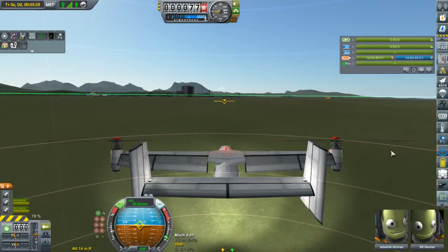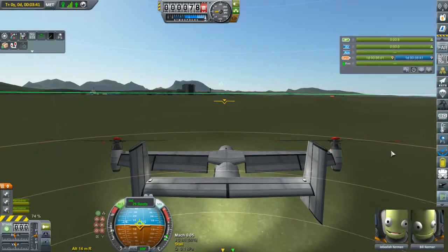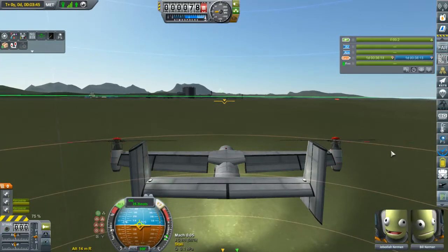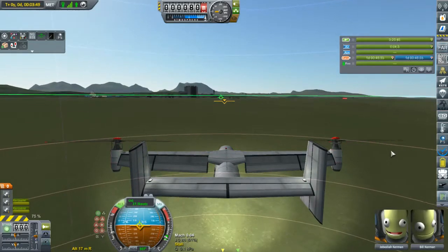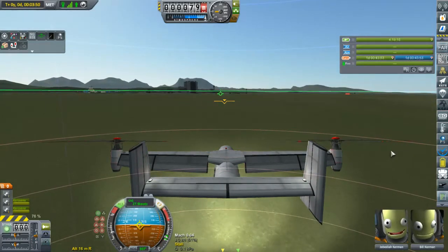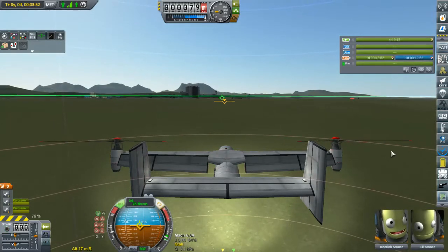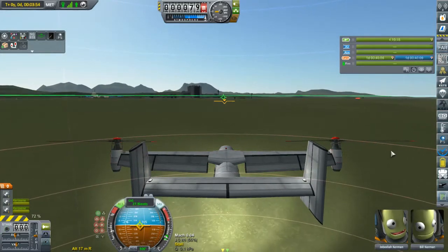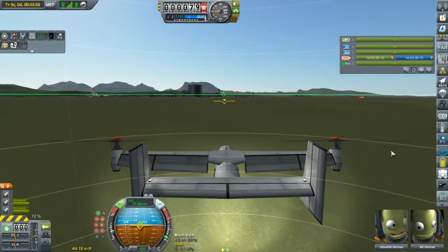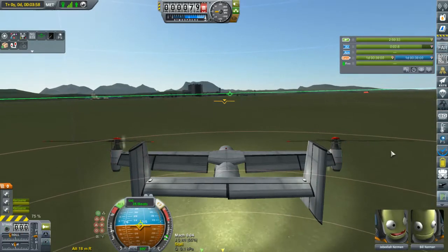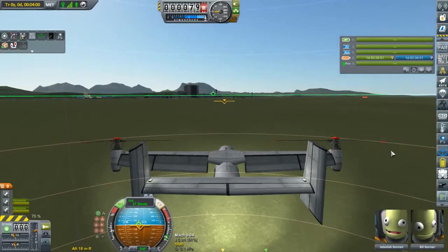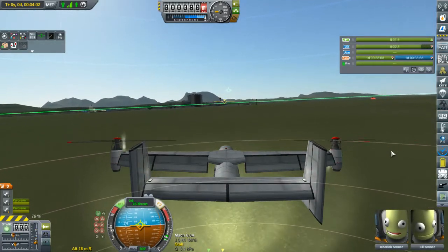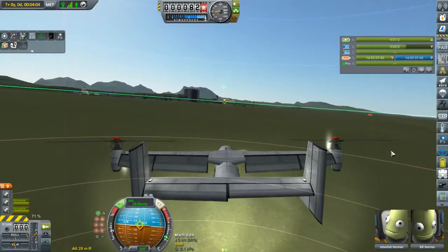As you can see, there is some slight behavior that the conventional tilt-rotor built-on engines just don't like to do, or don't like to counter. One, I've got immediate control of how much vertical thrust I'm getting, thanks to the collective, which means I don't have to wait for engines to spool. And two, because the cyclic is actually built in with some support from my thrusters, I have immediate response to the engines as well, and just rocking my stick around.